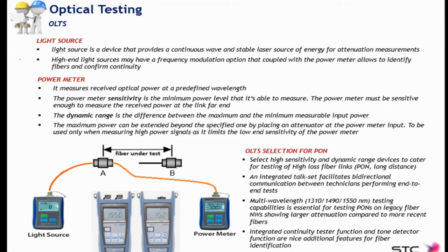They are not any type of patch cord. You connect them together at point A. Set your zero reference, pushing on the button, and then this power level at point A will automatically become zero for the power meter. One more time, regardless of the actual absolute power present at point A.